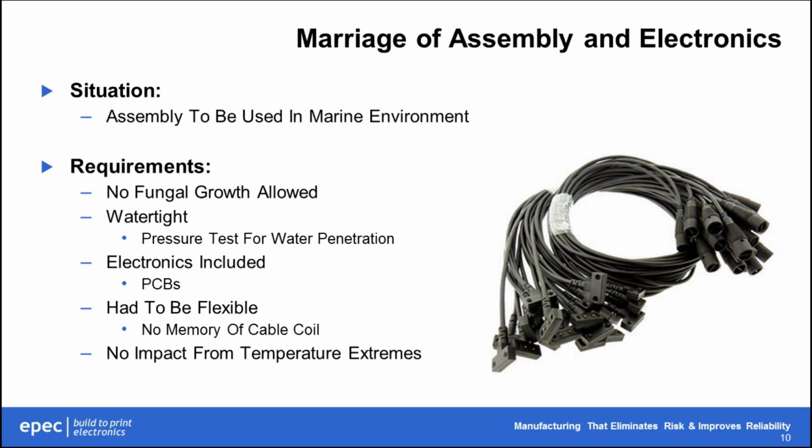Because of the exposure to the elements, the assembly had to be watertight, had to be able to work at all temperature extremes, had to remain flexible regardless of the temperature, and had to not allow any growth of fungus at the cable or the overmold area.